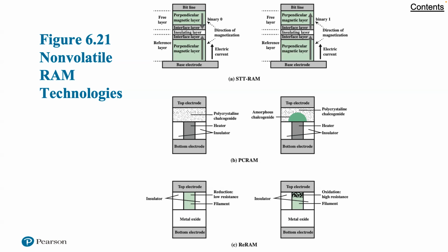Finally, ReRAM, also known as RRAM, works by creating resistance rather than directly storing charge. An electric current is applied to a material, changing the resistance of that material. The resistance state can then be measured, and a 1 or a 0 is read as the result. Much of the work done on ReRAM to date has focused on finding appropriate materials and measuring the resistance states of the cells. ReRAM designs are low voltage, endurance is far superior to flash memory, and the cells are much smaller, at least in theory.